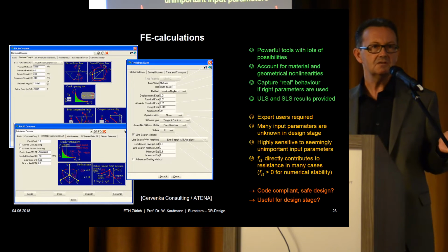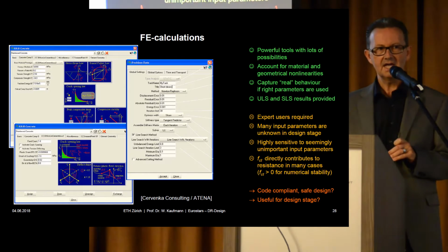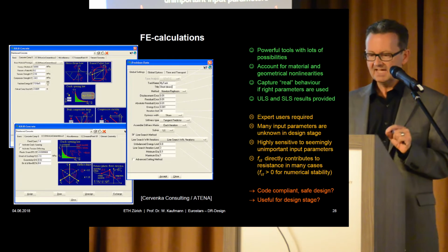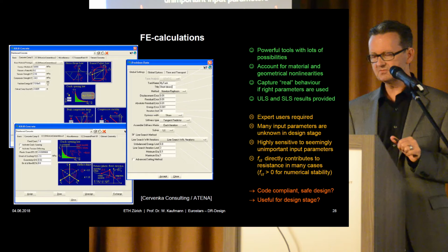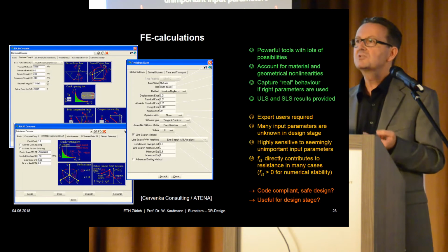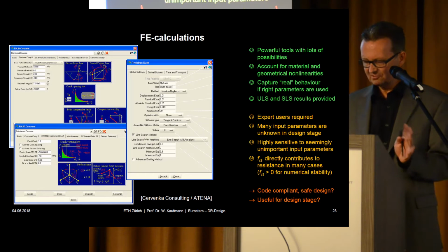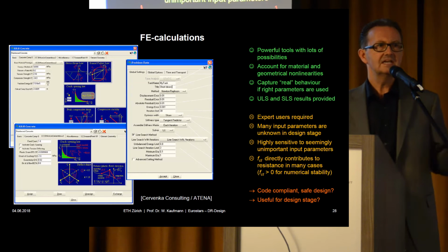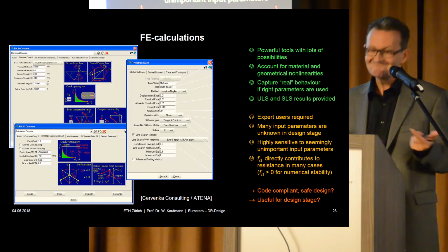Okay, why is that? If I do a stress field for these, and I use 10% of the tensile strength of the concrete, I can often also prove that it stands. But we don't want to rely on the tensile strength. And in these models, depending on which material model you use, there are some with a minor influence of tensile strength, others have a higher one, and even mechanical models like the modified compression field theory, by the way, always have an average tension in there. So that's something that I don't like too much, because our design philosophy should be, and it is, if you do conventional calculations, to neglect the tensile strength of the concrete. So why should we account for it when we do a nonlinear calculation? Not so sure.